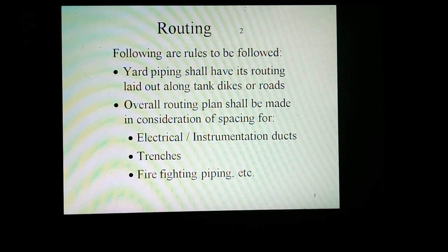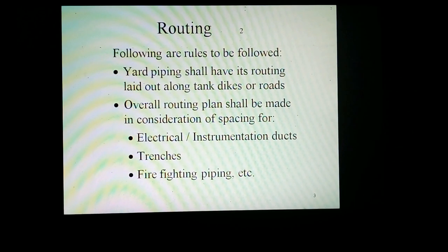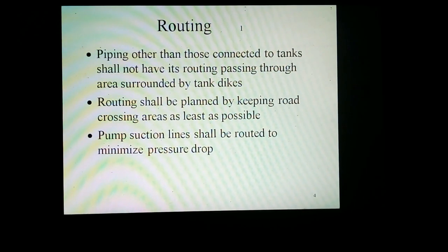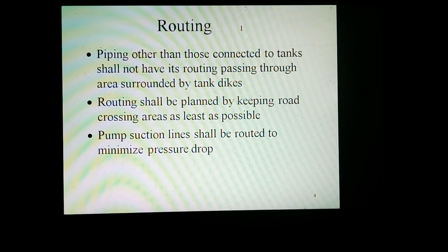Following are the general notes with respect to the routing. Yard piping shall have its routing laid out along the oil dikes or roads as much as possible. An overall routing plan shall be made in consideration of spacing for electrical instrumentation ducts, trenches and firefighting piping, etc. Piping other than those connected to tanks shall not have its routing pass through the area surrounded by oil tank dikes. Routing shall be planned by keeping the road crossing areas as few as possible.